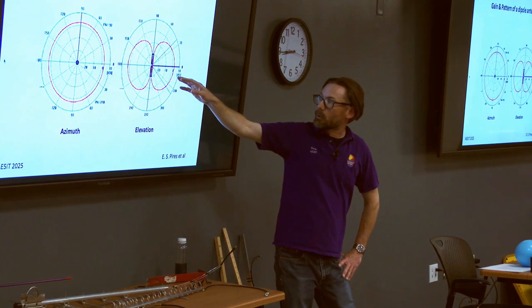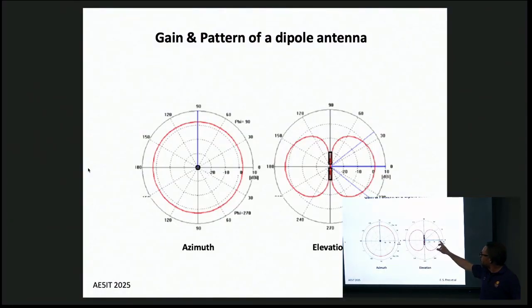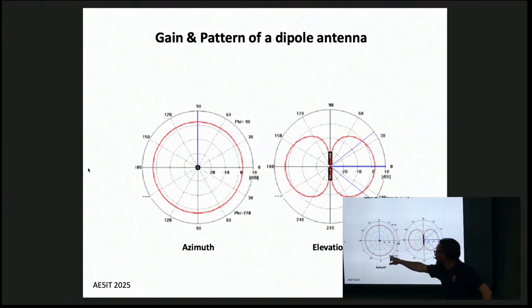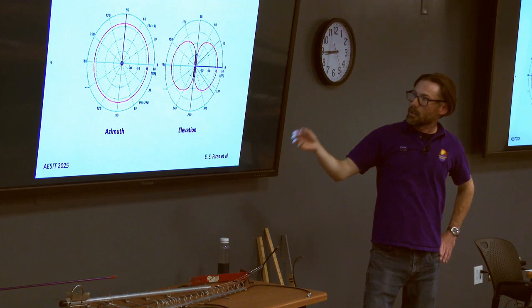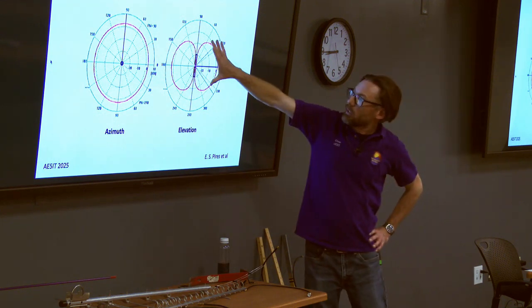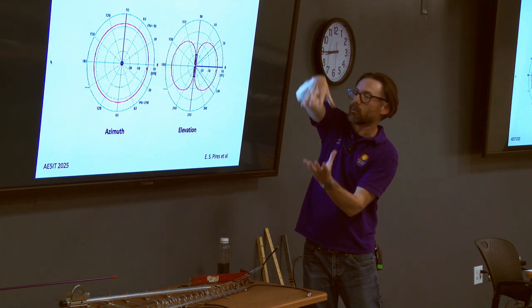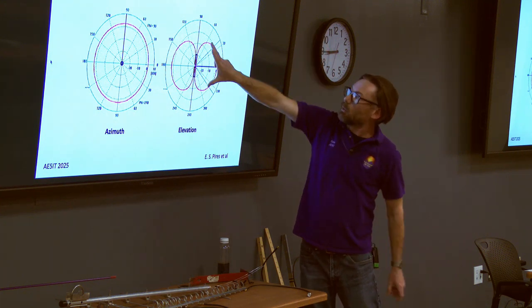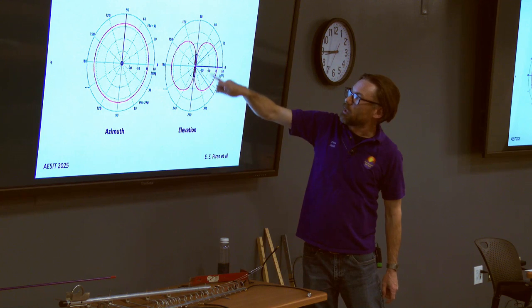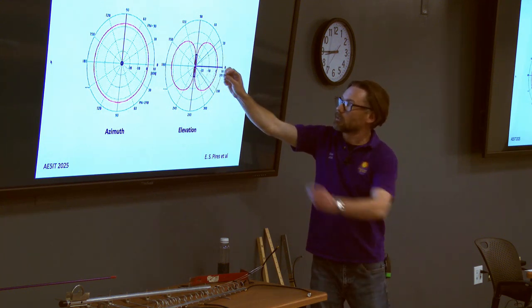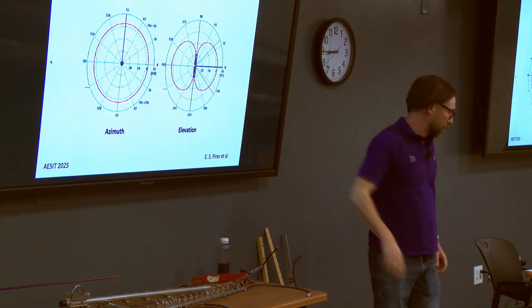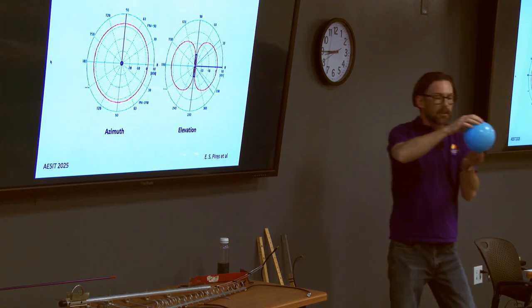Well, this dipole that we've drawn here is actually a little bit past the 0 in our azimuth in all directions, because of the radiation that we have taken out, right? The isotropic would have radiated in a sphere. Well, we have removed what would go straight up and down, and it has been redirected everywhere else. So that's our little balloon here.